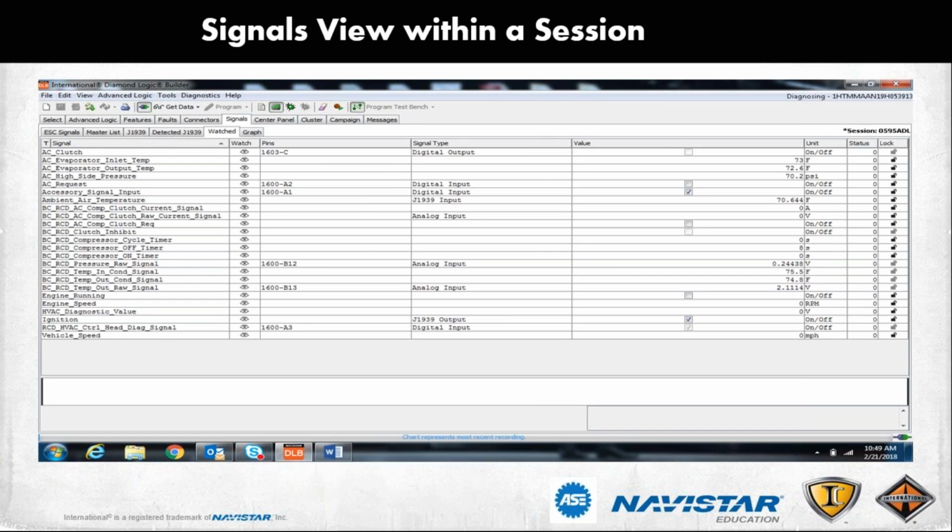In this picture, if you look close, it's showing no check marks in the wipers. The wipers are off. The park brake is set. The door switch is open. So if you look on the left-hand side, it shows you what your air pressure gauges are reading, your fuel level. Here you see high side pressure transducer, what it's reading. So we can look at all the signals in and out. So you go to our diagnostics manual, and it's going to give you the criteria that's got to be met before an AC clutch will engage. That's what we're going to use for our diagnostics, is that manual.